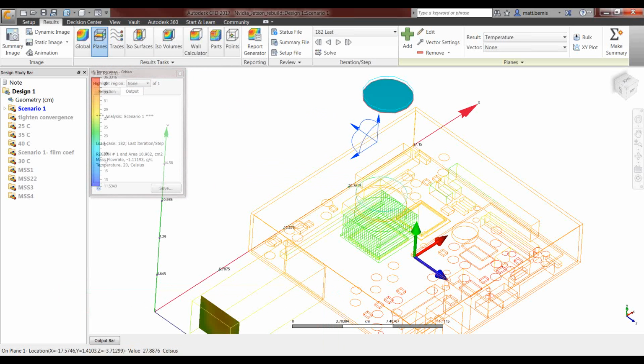One last question we have here is, why not emphasize mapped mesh for the heatsink? I suppose that means extruded mesh. Well, the extruded mesh only works for when you have the beginning and end surfaces identical, which is not the case for the air volume between the heatsink. It may be for the heatsink itself, but not for the air inside of it. But it's something to try, sure.